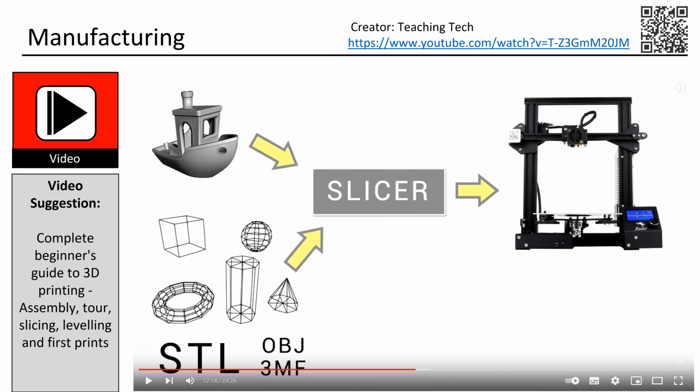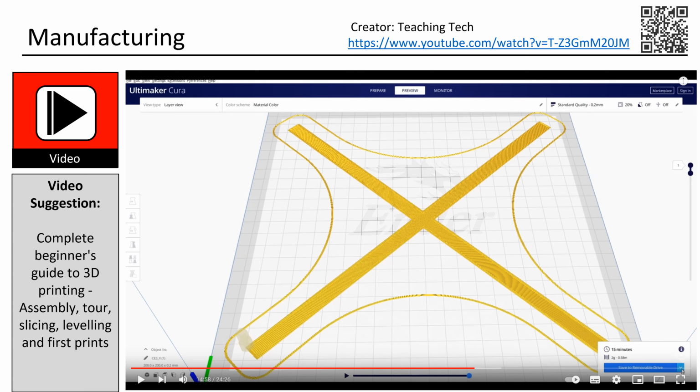You will mainly use .stl files. They go into a slicer and there the G-code is created. That is the code that the machine can read. There are many slicers, but Cura is still a good choice.